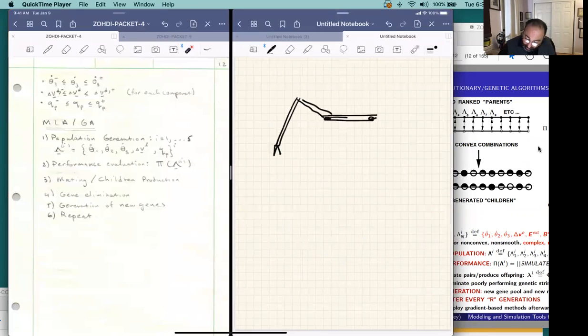In other words, as you're doing your analysis, this thing is just going to be moving up and down. You have to make sure that it's always remaining horizontal by simply implementing it and forcing it. So as your robot is moving around, you stipulate in the algorithm that the plane here is always going to remain horizontal.